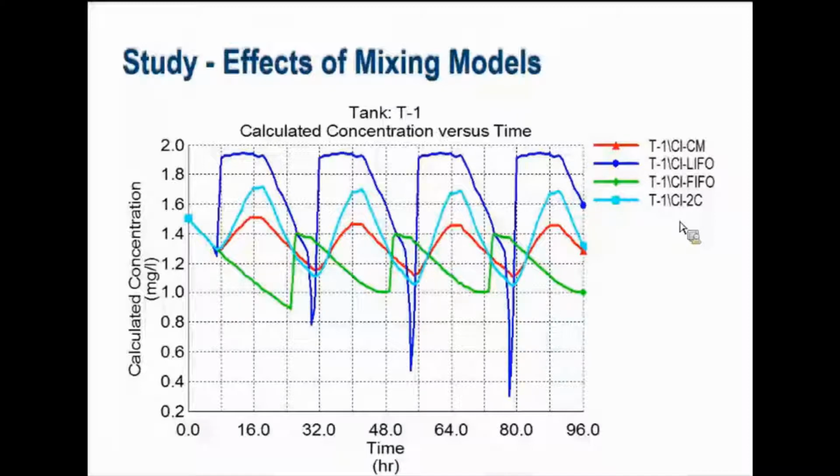Whereas the completely mixed one, the red one, you can see that's got the most narrow band as far as performance of the tank, because it's assuming that as water comes in, it's completely mixed in concentration with the rest of the tank, and whenever it leaves, that's a completely mixed concentration leaving. It does tend to matter, the tank mixing model, so I would encourage you to really understand the tanks that you have, how the flow moves in and out of those tanks hydraulically, if you have any devices there, no devices, where the inlet is, where the outlet is. Also, what is your confidence that it's very well mixed?